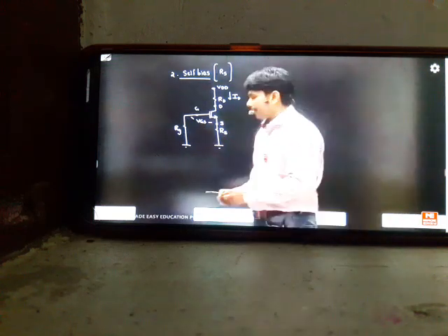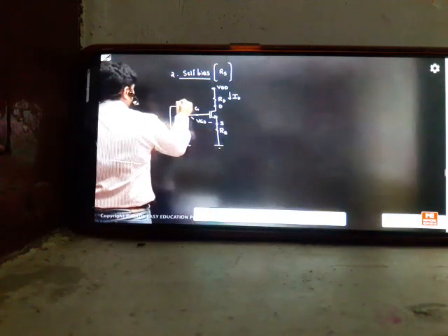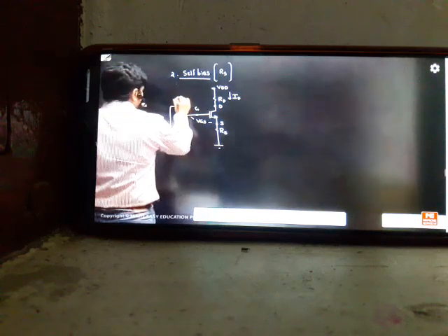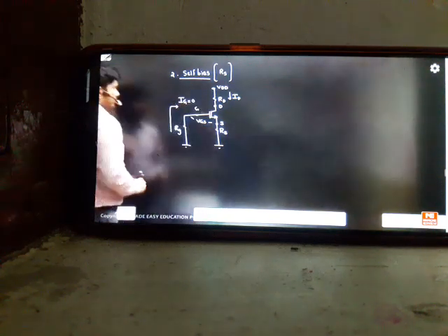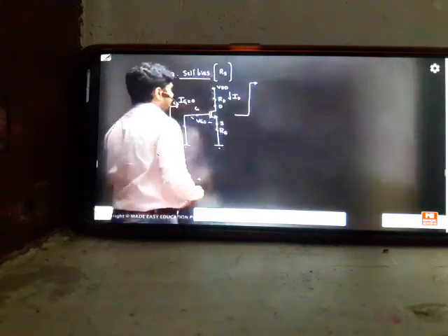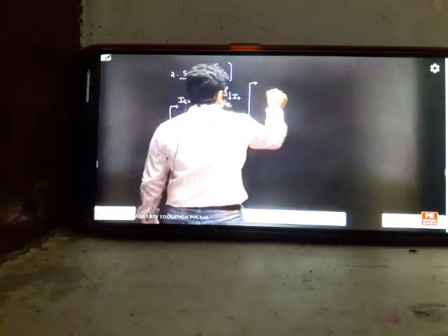So for this first story, I'll apply this. The gate current IG, capital letter, in DC analysis we can take as 0. No current will go into the MOSFET. Then this model can be represented, you can convert the model like this.